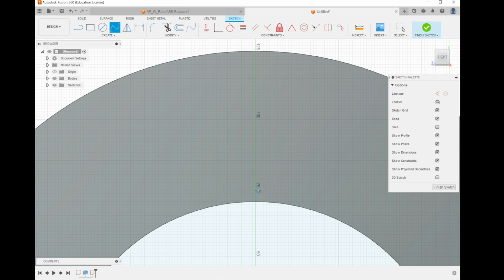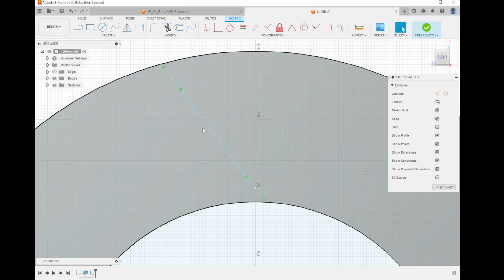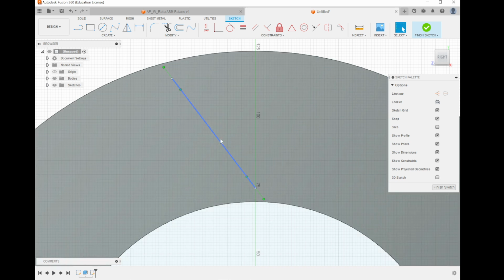Fixed point spline, we press our starting point and we press our ending point. So I want to end it out here. And then we press the enter button. So now this over here is a spline. We see that we have the blue line in the center and we have these green parts out here. For those doing accelerated maths, what's happening here is these green lines are making the derivative. They're changing the angle of the curve.